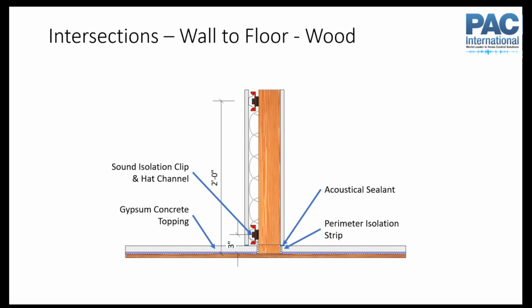Wall to floor, order of operations, there are a lot of different things that go into the consideration of order of operations. Do you frame it first and then do your gypsum concrete and then come back in and put in your drywall, or all these different things? Different people and different regions are going to have different preferences for how they do this. But the thing that you need to pay attention to is making sure that things that are supposed to be acoustically isolated stay acoustically isolated.